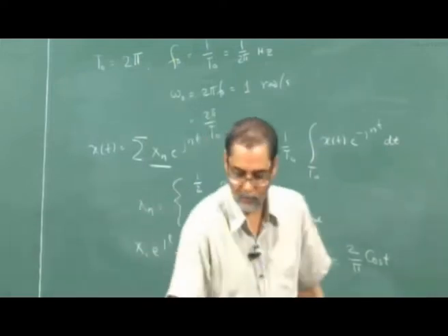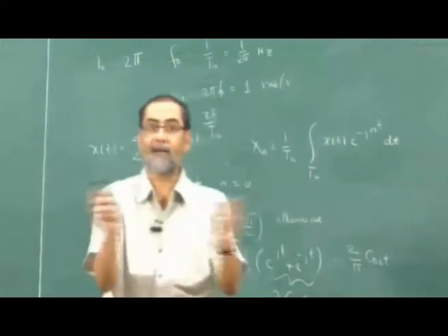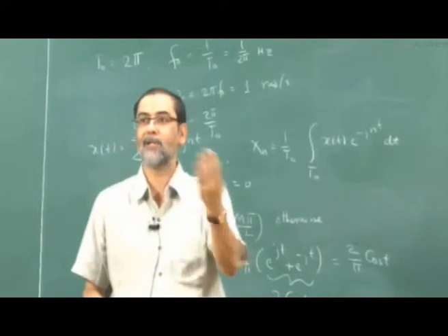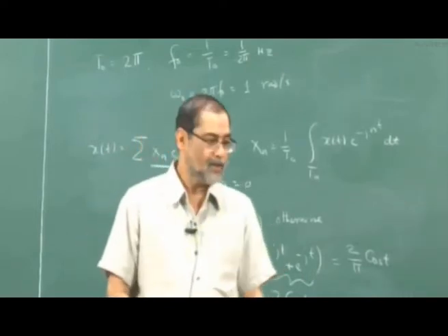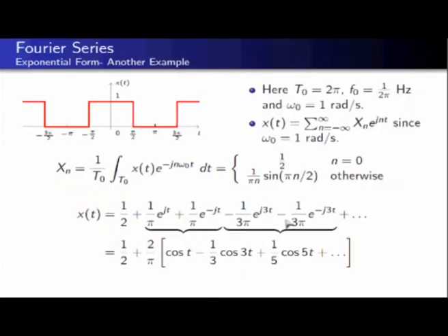That is what I am going to do next. So collect terms of equal powers of exponentiation and join them. So for the rectangular pulse periodic signal x of t shown on the top left by that red curve, I now have a compact Fourier expansion in the trigonometric form, because exponential is slightly difficult, so trigonometric form.